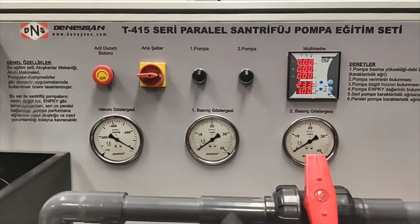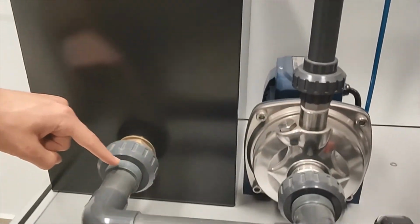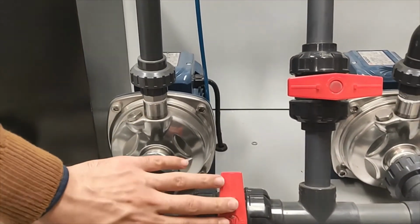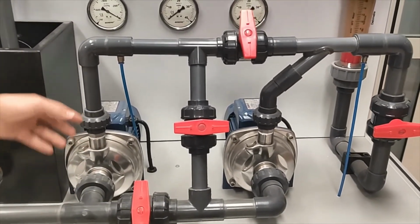Okay, firstly a single pump setup should be done. The water flows this way for the single pump setups. The first pump should be open. The first valve must be closed, which is this one.